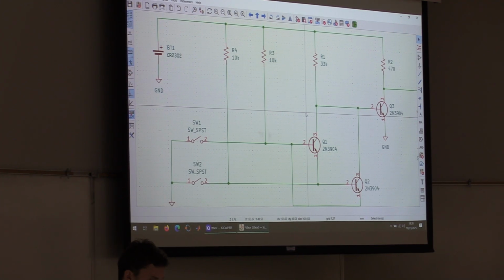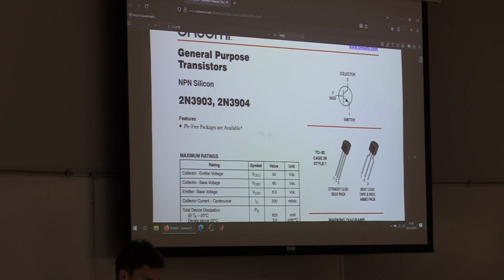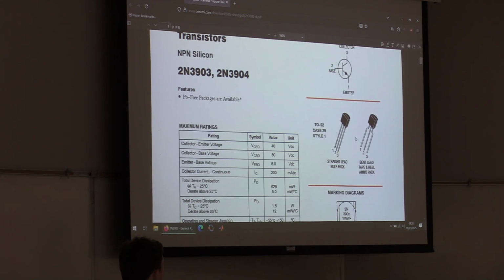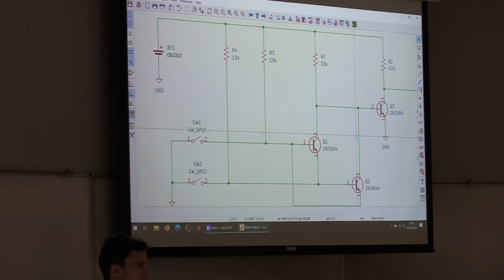In the case of our transistor, you can see it's a three-legged component in what's called a TO92 package. Now with every component you find, it'll list the package, which is the physical shape, dimension, type of legs. It's a standard way of creating parts. And that package will have a footprint to it. Most of those packages are in KiCad.